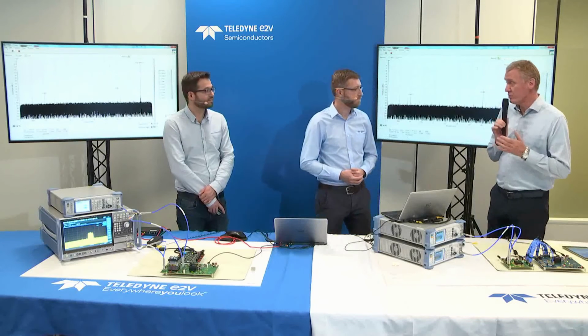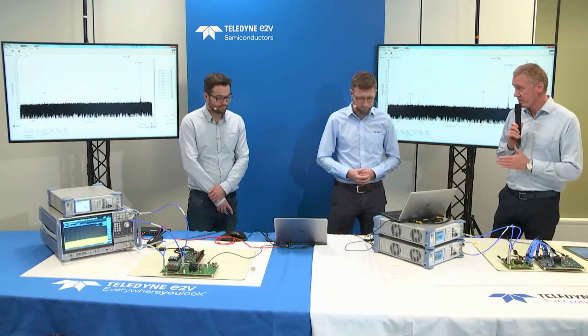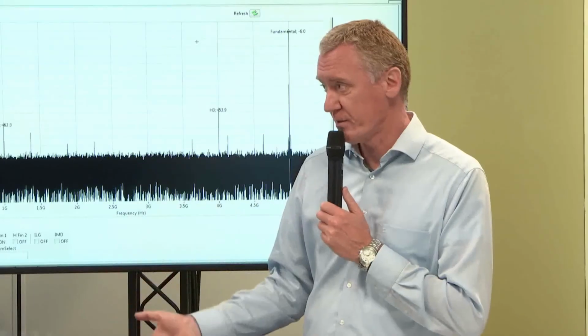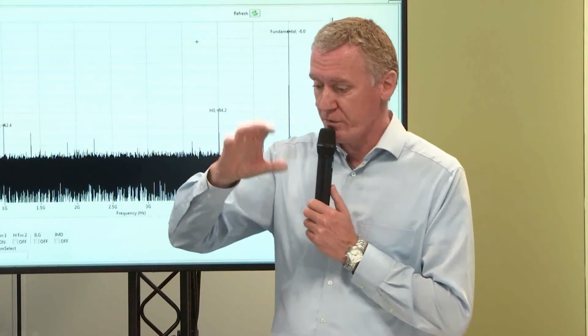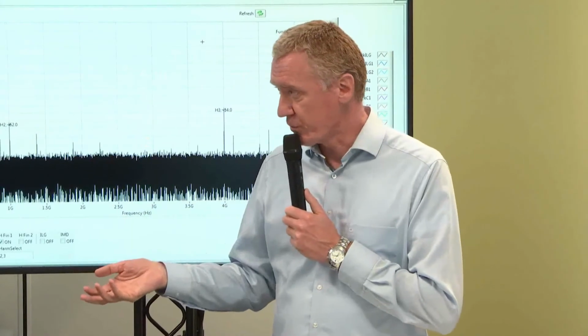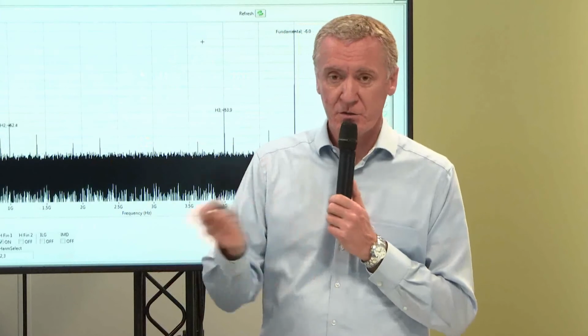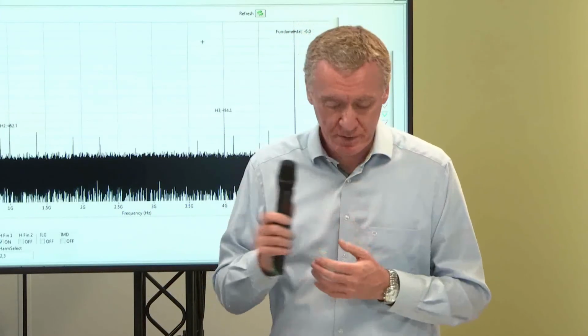That's the great news. Up to Ka band, frequency down conversion or downconverters are no longer necessary. If the system works at a higher band than Ka, we need frequency down conversion, but certainly fewer stages of down conversion. That's a cost saving and multiple benefits.